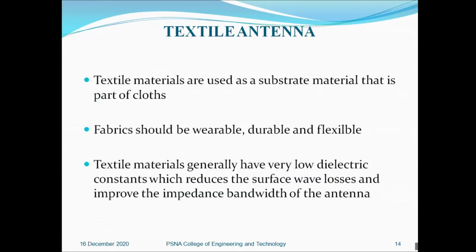So the textile material can be used as a substrate, which is nothing but a piece of cloth. What we are discussing is how to calculate the dielectric loss and how to select the dielectric material. We can select any dielectric material, and there are numerous methods available, even in IITs like IIT Kanpur and IIT Chennai, and also in the laboratory we can do it on the microwave bench itself to measure the dielectric constant.